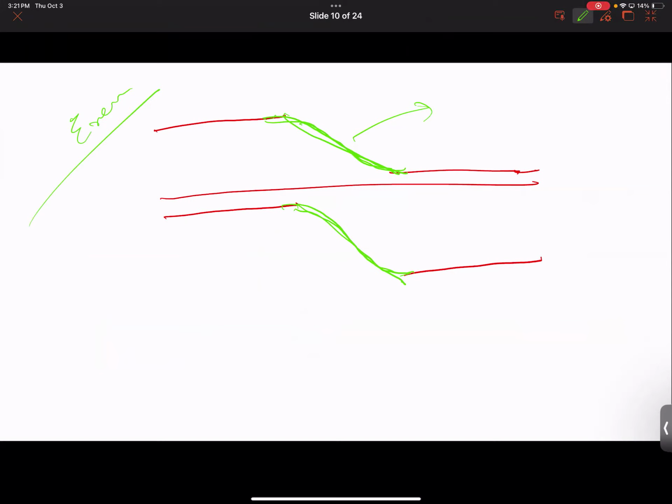And by the way, notice, where are we making this curvature? This is xp. This is xn. That's where the connection occurs, exactly at that point. This is the space charge region. In the middle, you have the metallurgical junction. Are you guys with me so far? So there is reason behind drawing everything. Are you all good? Okay, sure.